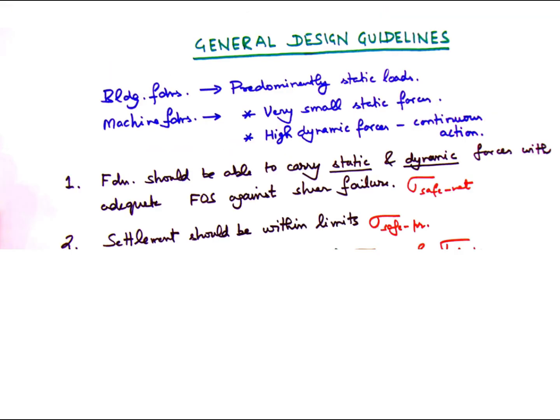The next important consideration is that the settlement under the foundation for both static and dynamic loads together must be within safe limits. So the pressure corresponding to the settlement criteria is called the safe bearing pressure.